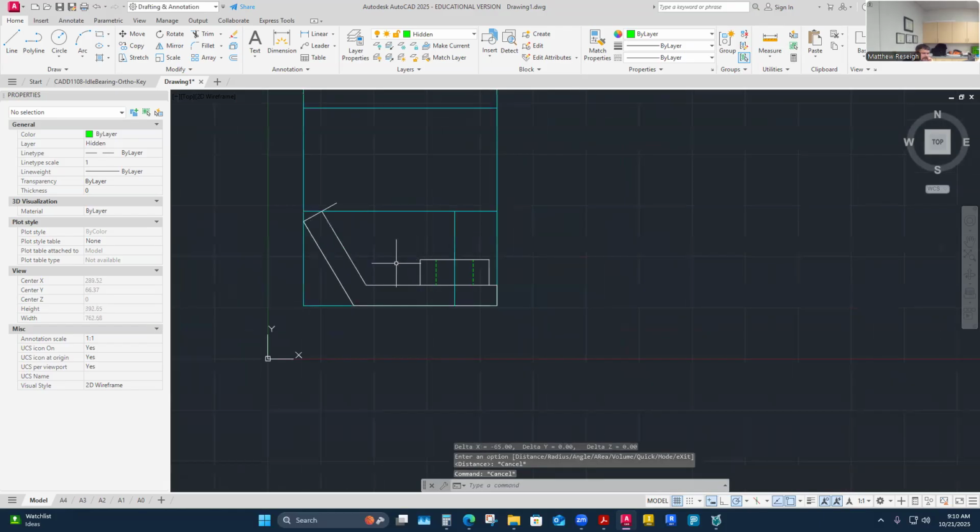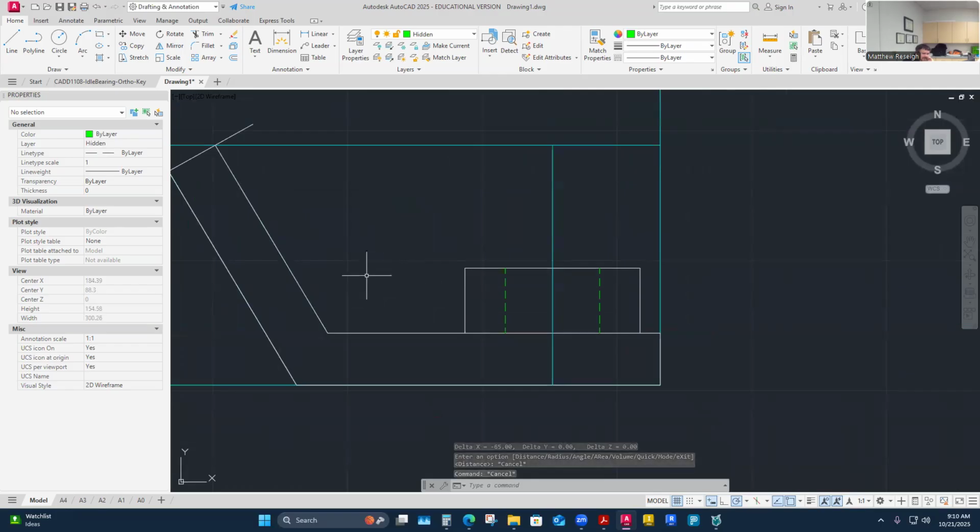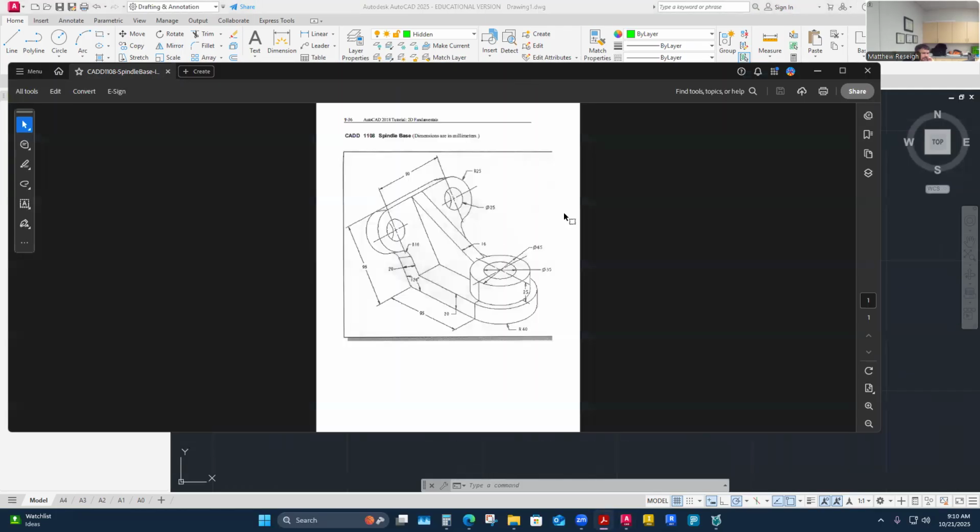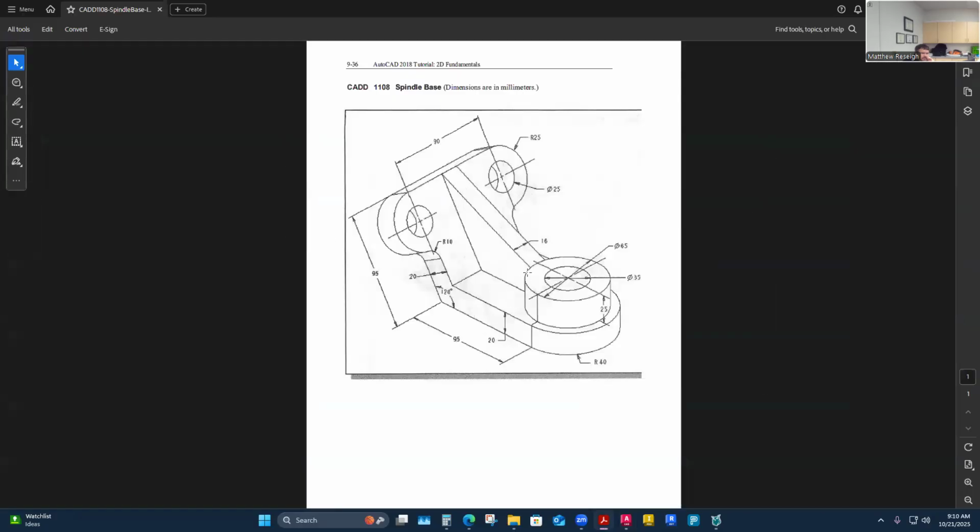That should project correctly. And then I just have this gusset. I kind of consider this feature a gusset. And maybe this is a 3D printed part, all uniform. Maybe this is actually three different pieces. If something was built out of metal, this particular piece could have been cut out totally flat and then bent. So we have press brakes that will bend metal up to certain thicknesses. We can bend really thick metal, but it does cause huge radiuses on the external and internal places where it bends, where that material stretches and forms.